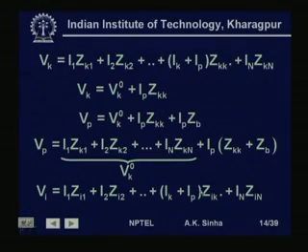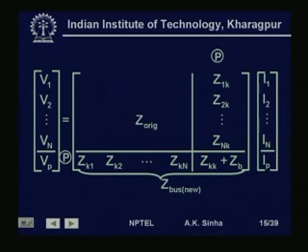So, what is happening at the kth element impedance for that row is not multiplied by Ik now, but it's getting multiplied by Ik plus Ip, because now this is the modified current injection at bus k. So if we do that, then we can write this whole thing in matrix form as V1 to Vn, Z original.